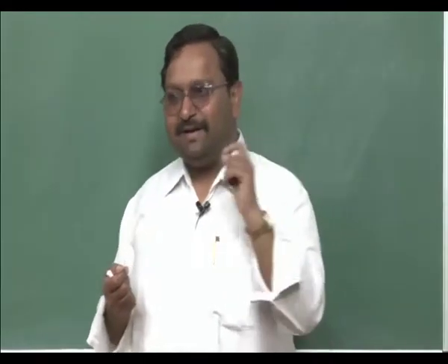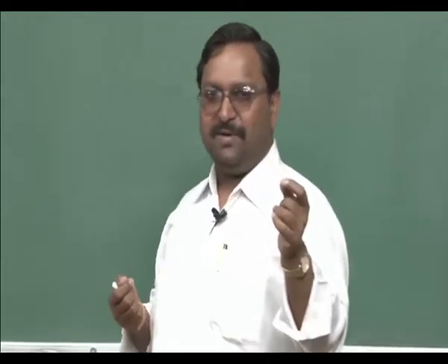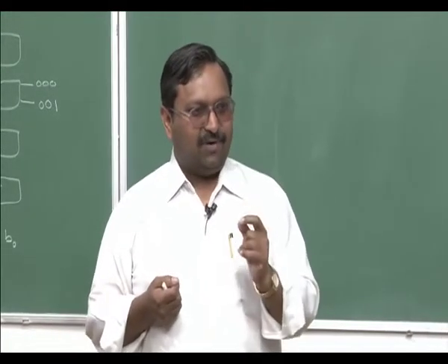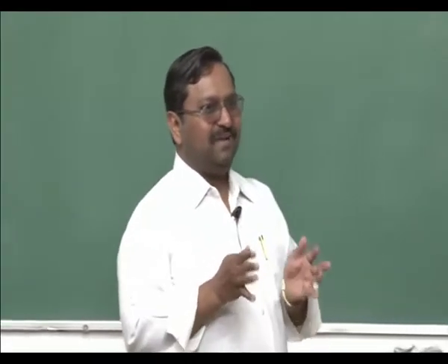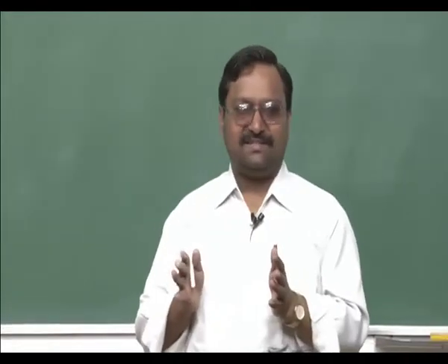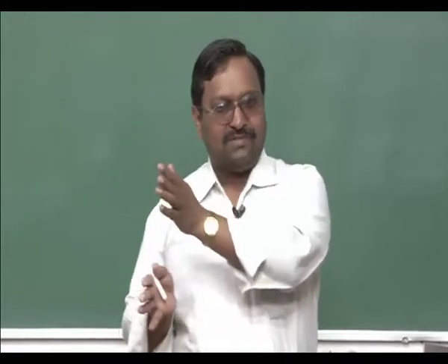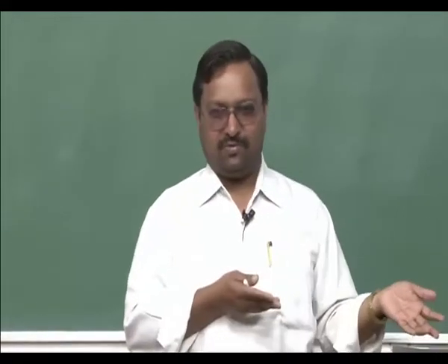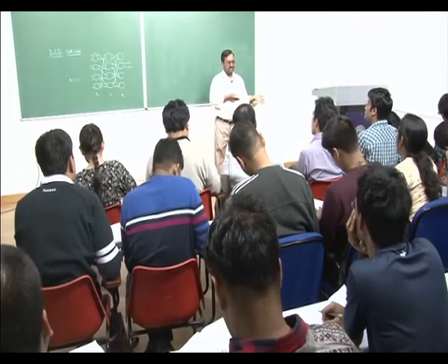There has to be exactly one connection from a switch in the previous stage to the switch in the next stage. Another important thing, none of the inputs and outputs will be left free in the intermediate stages. All outputs in the output stage will be the outputs, and all inputs in the input stage will be the inputs to the switch matrix.